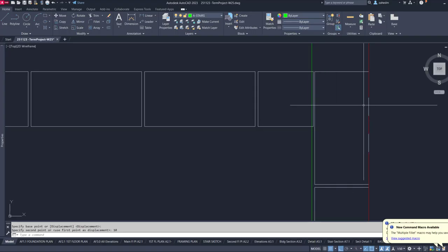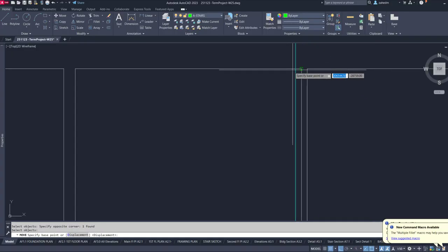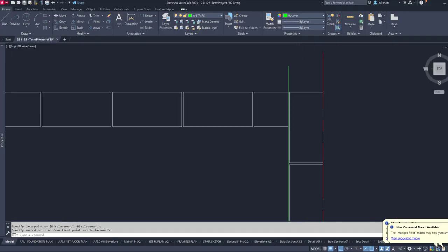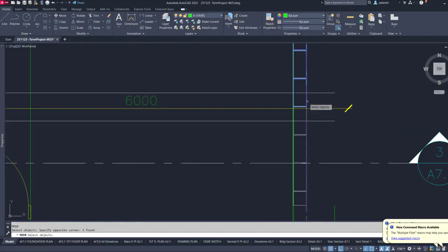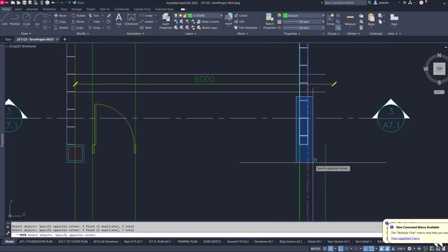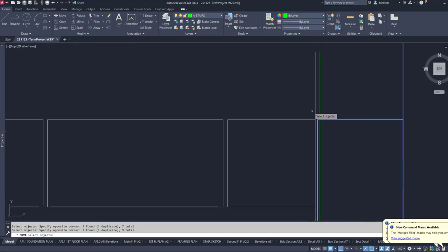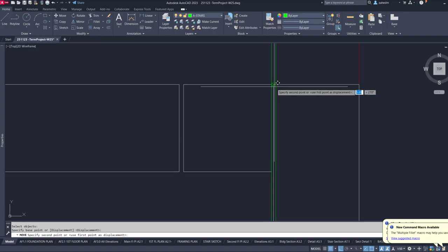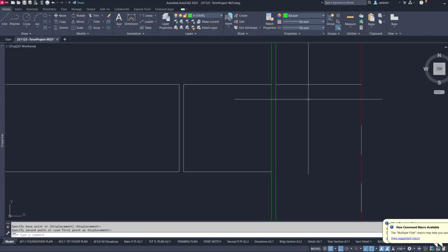Now I have a little bit of mortar joints, and this is going to sit exactly where it needs to be seated. Let me move this. This is the job of the architectural technologists. They are going to come to an exact conclusion of the sizes. In this case, I have to have 10 millimeters of mortar joints. Then the numbers might change a bit, but don't worry, because you are the people to call for the real exact number in the end. So I'm going to put that back in here. Now I have exactly 10 millimeters of mortar joints.